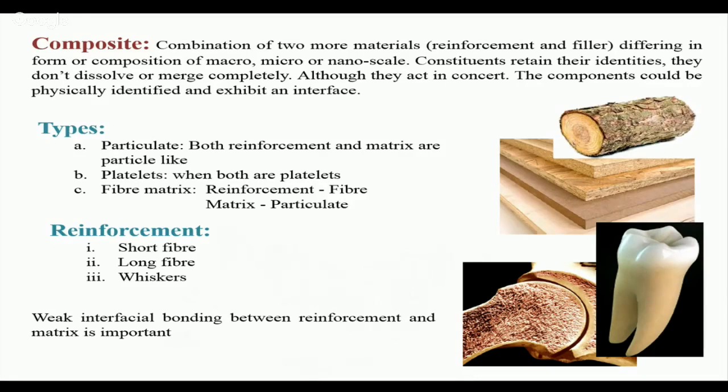But in case of nacre, or in case of snails or pearl, there are platelets, and in between the platelets there are proteins. These proteins act like a shock absorber, and these platelets are intercalated. So they are intercalated so that if cracks initiate, they cannot go in a straight line, rather they proceed in a zigzag way. That is how they can act as reinforcement or toughening.